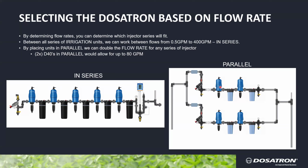And why that's important is that if we're not fully at 80 gallons per minute, there's a chance that a higher portion of that flow could be traveling through one of the injectors versus the other. If they're set to the same rate and they're injecting the same thing, we're still going to achieve the proportionality of injecting a set amount per gallon of water for every gallon that travels through.